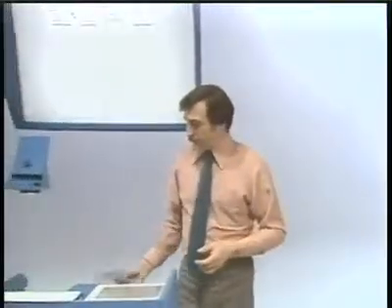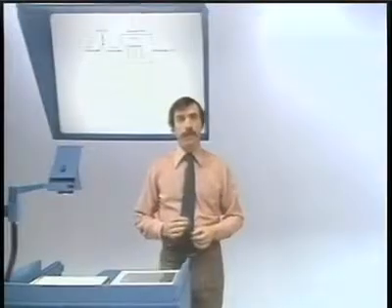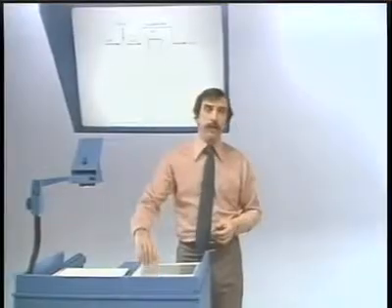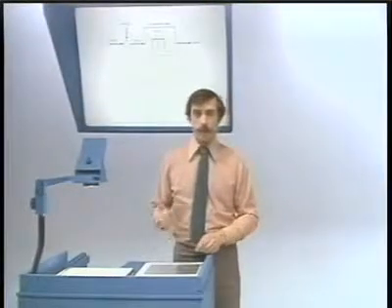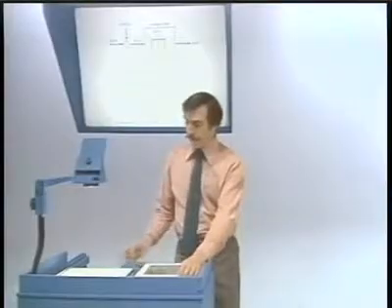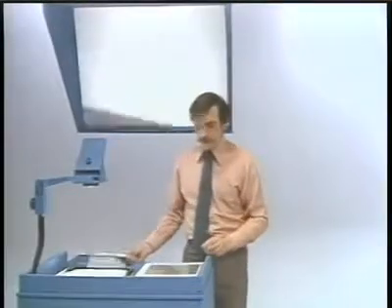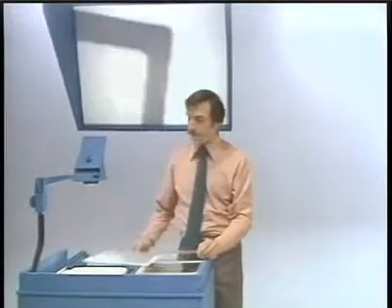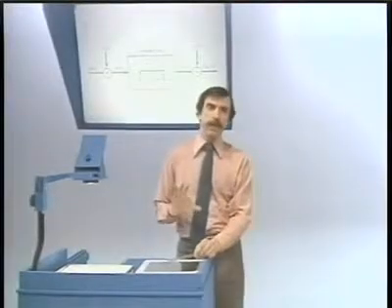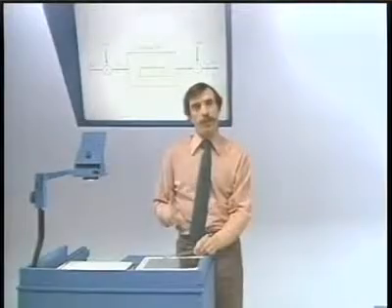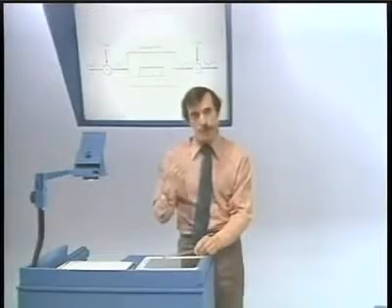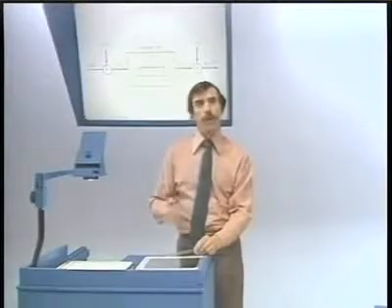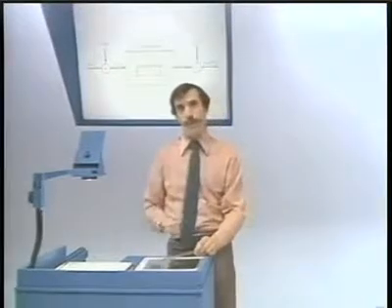Okay, now there is another application that we have discussed for both continuous time and previously for discrete time, amplitude modulation with sinusoidal or complex exponential carriers. And let me just remind you of that because it becomes a very important one in the case of discrete time systems. And that is the notion of using modulation together with fixed filtering to implement a filter which either has a variable cutoff or converts, let's say, a low-pass filter to a high-pass filter.